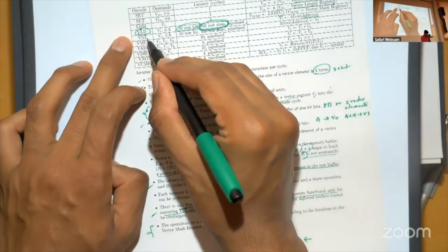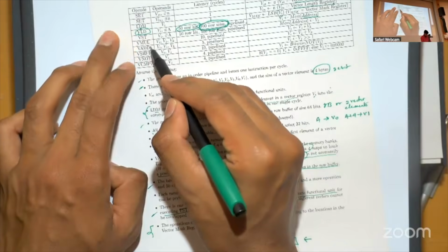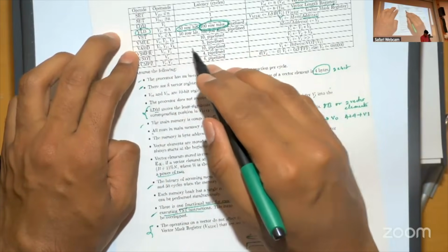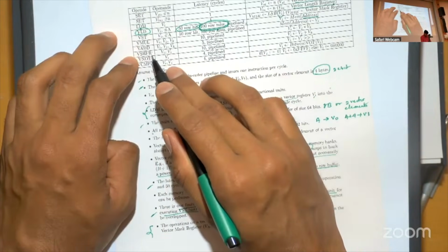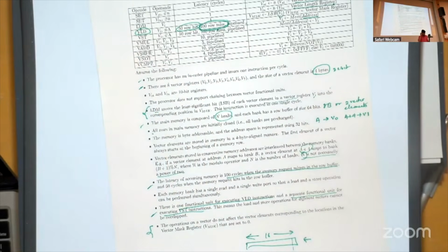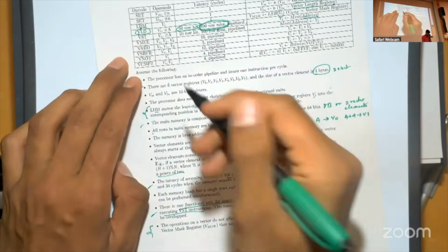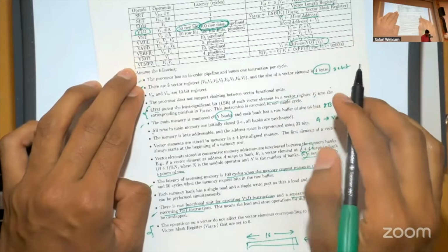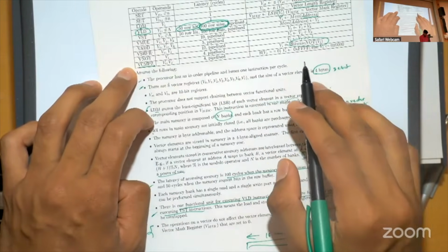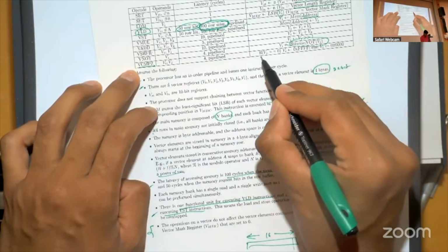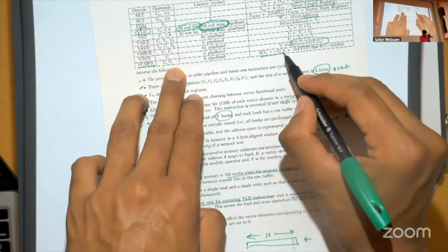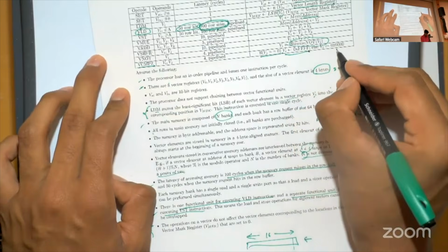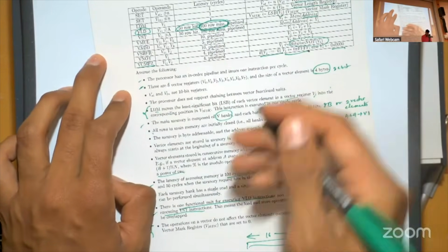We have already seen VLD and VST. We have VMUL, which takes 10 cycles to perform multiplication. It's pipelined. We have add, 5 cycles, pipelined. We have shift right; you can shift right by 1. And then you have VNOT, which performs the bitwise NOT of VI and restores it back into VI. And then you have the V compare if 0. So if you compare VJ to 0, and if it is 0, VI will be stored with all ones or all zeros. It's to compare if the values are zeros or ones.